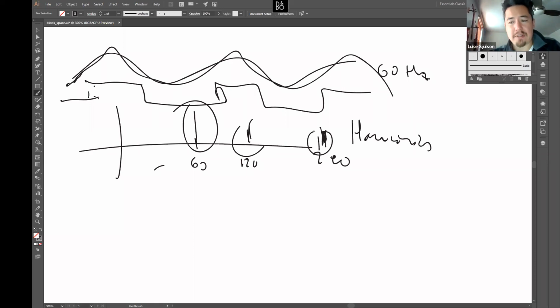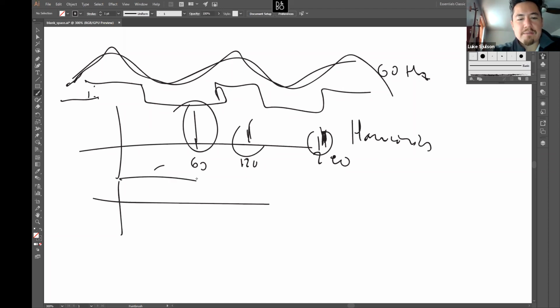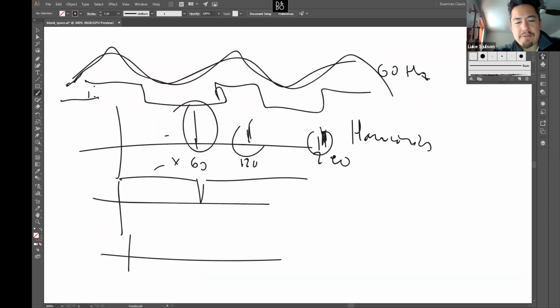Okay, a notch filter is a filter where its transfer function is like this. It has a notch. An example of a notch filter would be when you want to filter out 60 hertz noise. If that's your Fourier transform, then you should have your signal and it should be like that, and actually there'll be a little bump like that at 60 hertz. So notch filtering, and then you might have to notch filter the harmonics also. Okay, so notch filtering can come in handy.